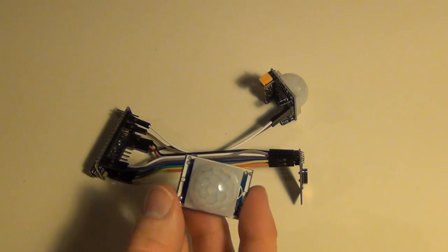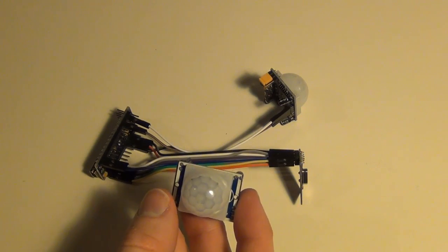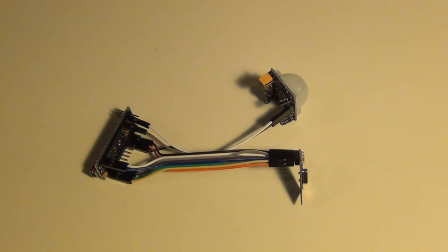I don't think I've ever actually had a piece of hardware go bad yet, but there have definitely been times where I've thought that it was the hardware and then swapped it out, had the same results, and then found the error somewhere else, whether it was in a wire, miswired, or maybe software error, something like that. So if you can, if they're cheap, multiple sensors is always a great step for troubleshooting, to just switch out that sensor to know that that's not the problem. Now there is a chance that you could get two bad sensors, which would be awful, but less likely.